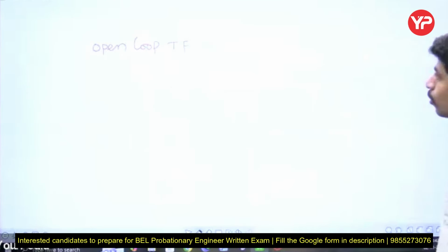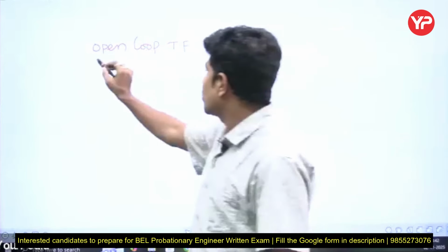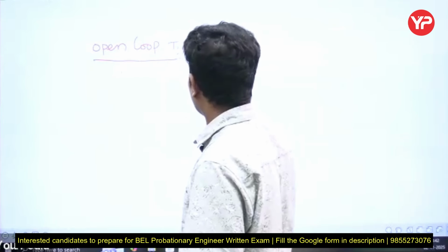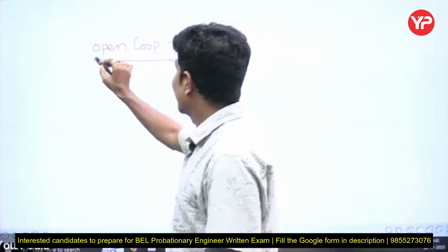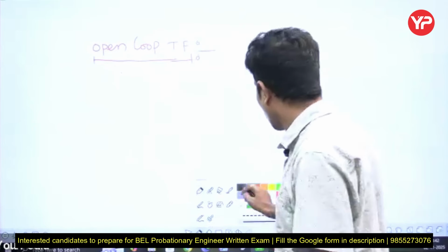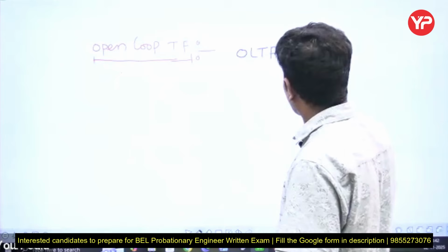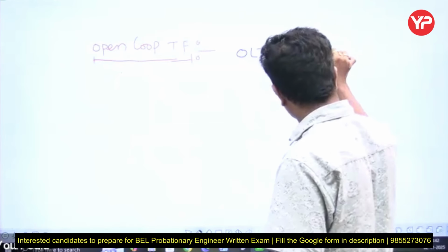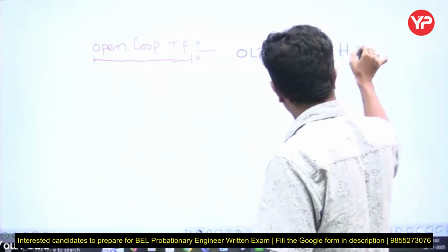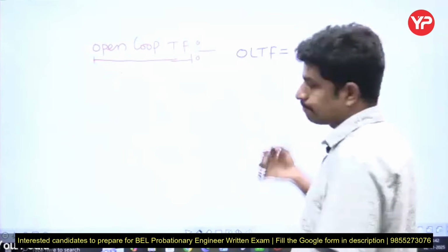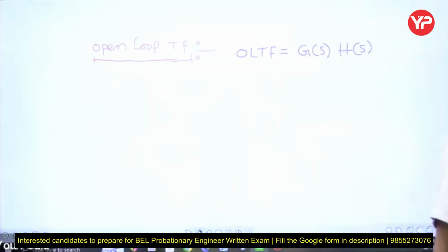What does open loop transfer function mean? Don't think that we remove the feedback and get the transfer function. No. Open loop transfer function means whatever you have in the forward path, into whatever you have in the feedback path. Don't misunderstand the term open loop.